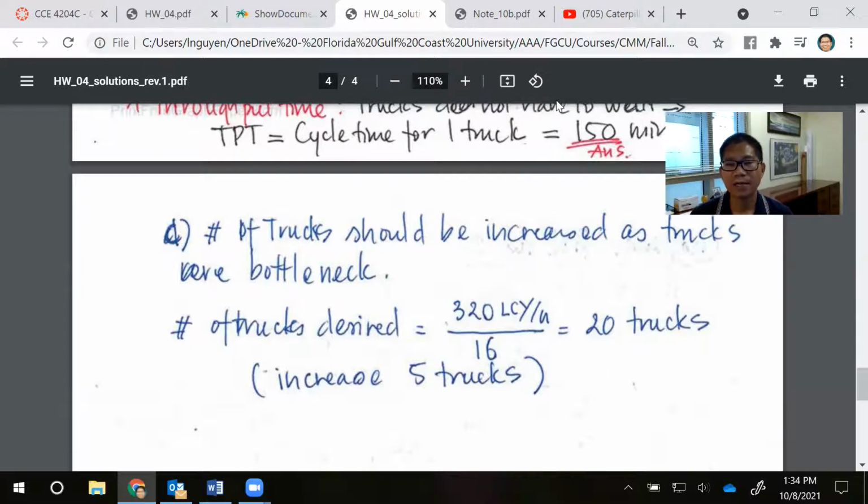So I hope you get the idea of how to model the process with this problem in terms of diagram: how to model tasks with rectangles, how to model the queue, inventory, and work in process with upside-down triangles, and the flow of information, which will be dashed arrows, and the flow of material, which in this case will be a solid arrow.